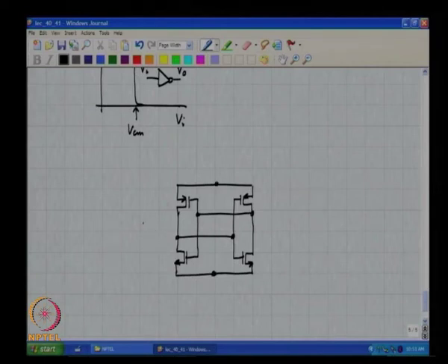Okay, and we know that we would not want to deliberately increase the parasitic capacitance at the input nodes for fear of increasing the regenerative time constant. In any case, there are so many devices, so there is bound to be a lot of parasitic capacitance. So, you can simply use that parasitic capacitance to hold the analog inputs. Is that clear?